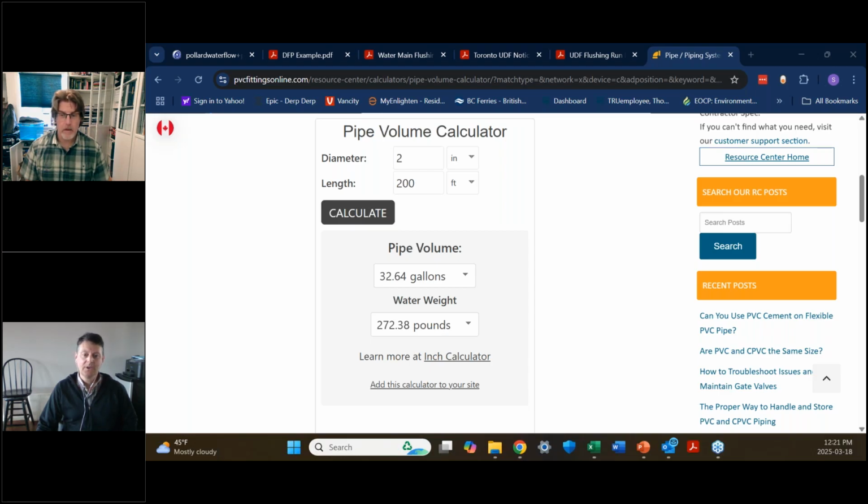We have a question from Arvid here. It says, when closing a hydrant after flushing, is there a recommended procedure to avoid water hammer? Nice and slow, Arvid. That's the nice and slow, right? That is the best way to avoid the water hammer.